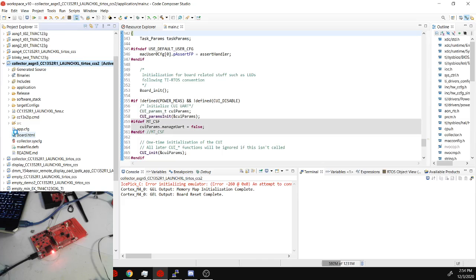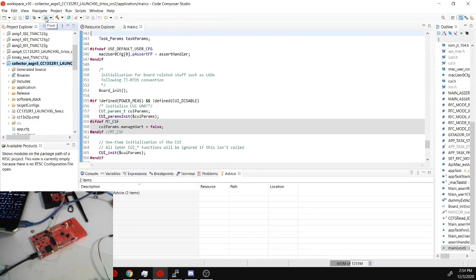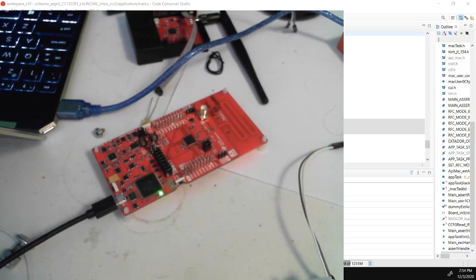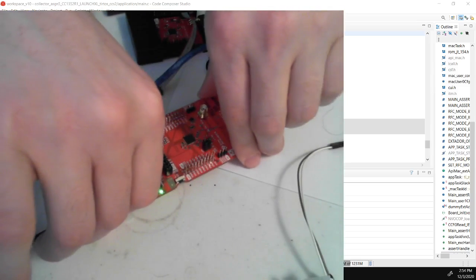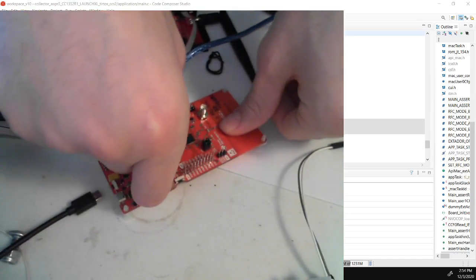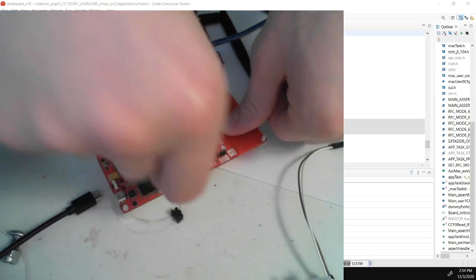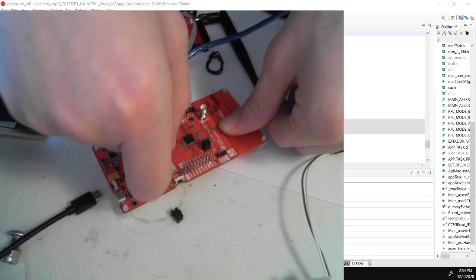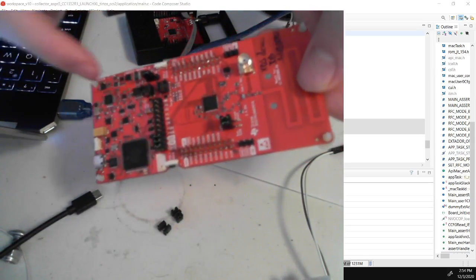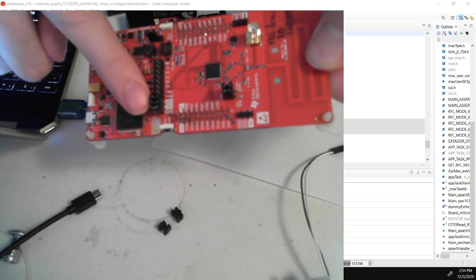Okay, very good. Now we're just going to turn this off. Leave debugging mode. I'm actually going to make the preview larger now, and I'll show you what I'm doing here. So I'm going to disconnect the board, and I'm just going to rip out all of these connectors except for the ground, 5 volt and 3 volt.